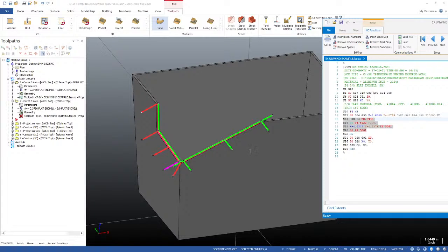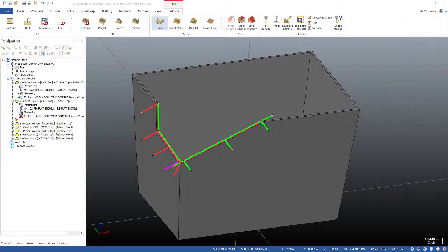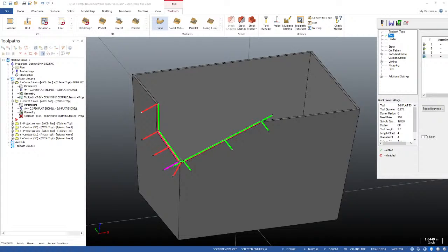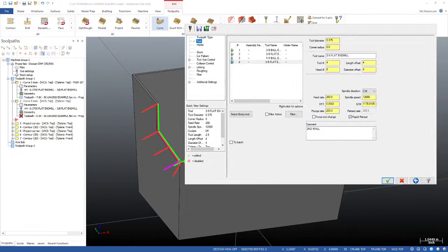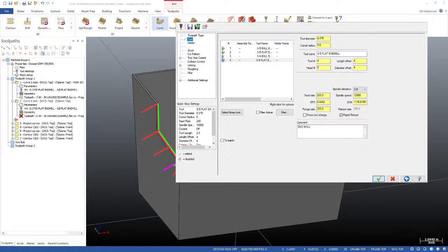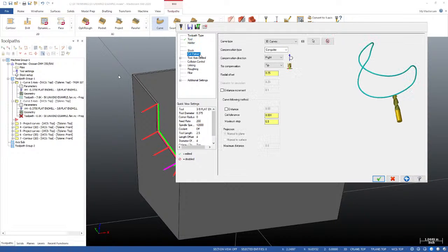Okay, so I'm entering my toolpath data here. Is that my toolpath? That's my toolpath. Let's get the toolpath in place. There we go. So under cut pattern, 3D curve, I'm going to do partial. I'm going to go the other way so that we can use left this time, just to show you.